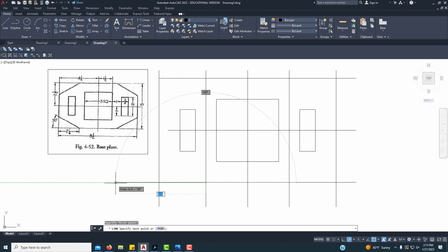So our angle is actually 180 minus 30, which is 150. So our angle is going to be 150. And you'll know that it's snapping to every 30 degrees because of the green dotted line that comes up. So I could try to get exactly where I needed to be on that line, or I could extend it out so I know that it's exactly 150 degrees.